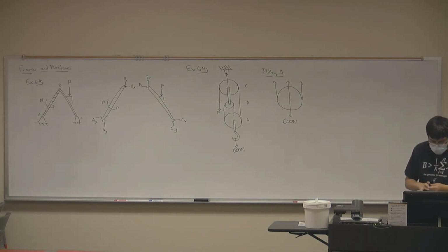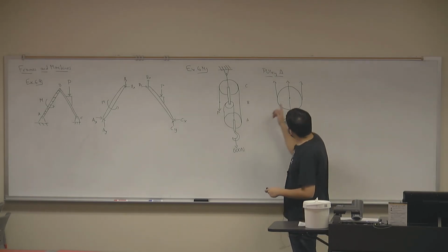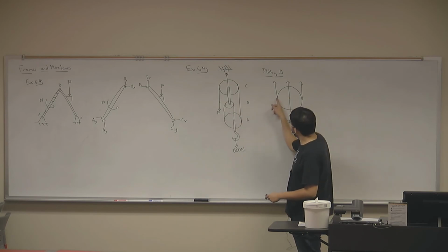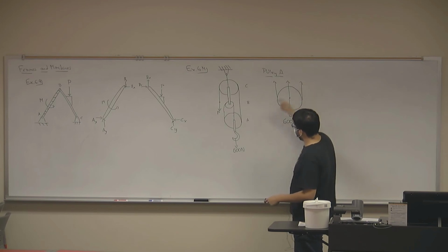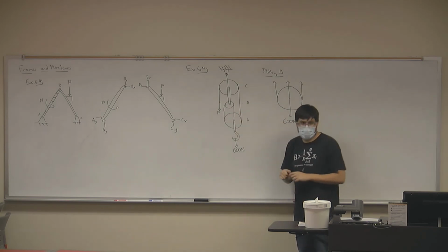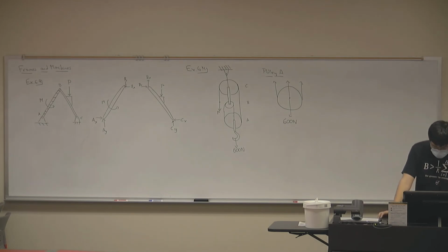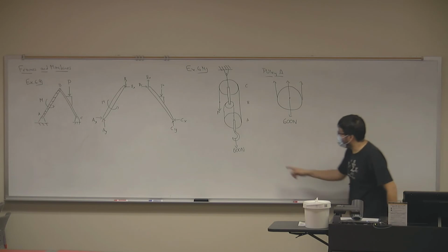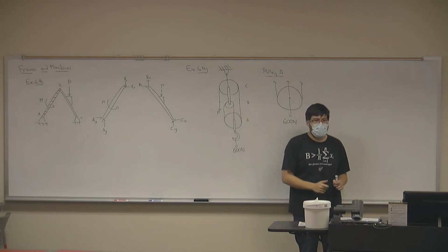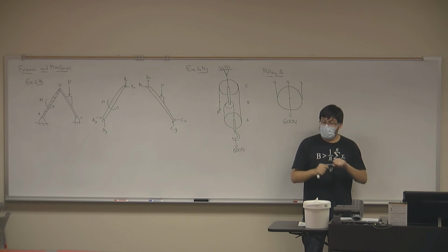But here's the thing. This force, and this force, what do they all have in common from this diagram? They're all in the same direction. What else? Like from the context of looking at this like a structure. They're all on the same cable. What do we know about cables? Cables experience tension equally everywhere. So then we divide it by 3.